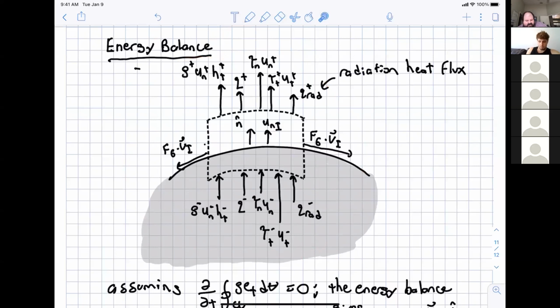It's just now when we do combustion and we have a high speed, high Mach number flow, we have all sorts of sources of heat, enthalpy, kinetic energy, and work. So we have work due to viscous stress. We have pressure work, which is part of the enthalpy. We have the heat flux, which accounts for heat conduction, species mass diffusion, and that whole big nasty thing that we showed earlier.